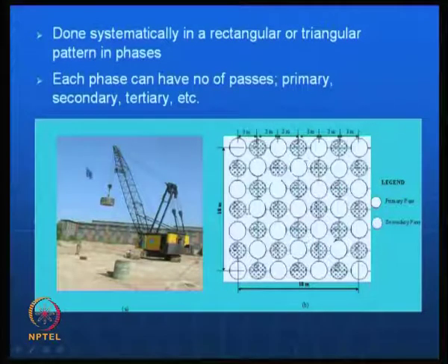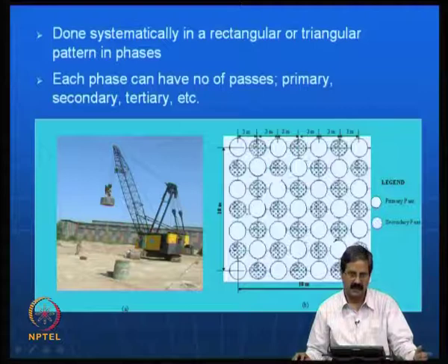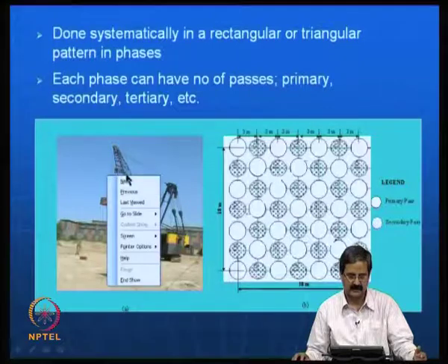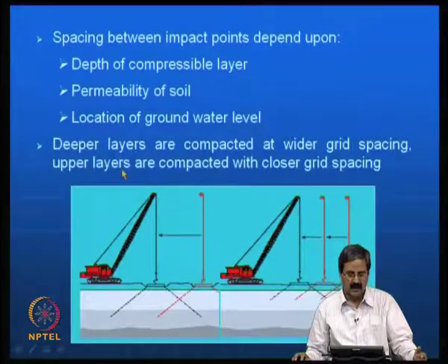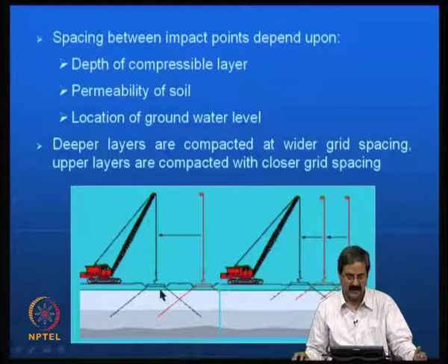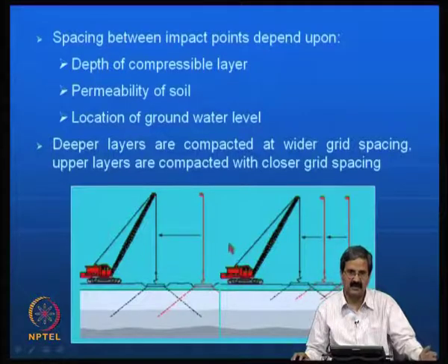So, you compact them in this manner, you can just see a circular weight, whatever it depends on the project. Based on this, one can compact the ground to about whatever is the depth one can go, like maybe 10 to 15 meters, one can definitely compact using these techniques. So, the spacing actually is an important variable here. The spacing influences a number of variables, like say for example, if you want to go for large depths, you need to have wider spacing.